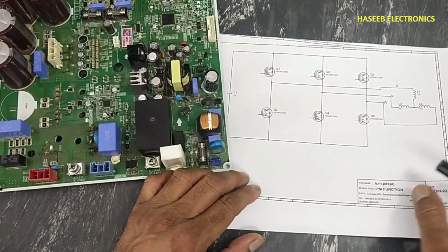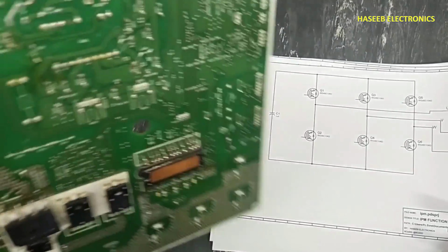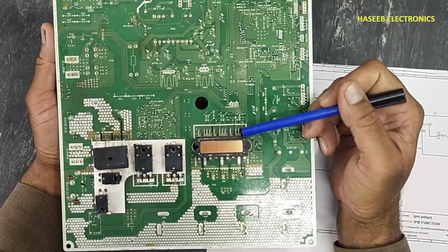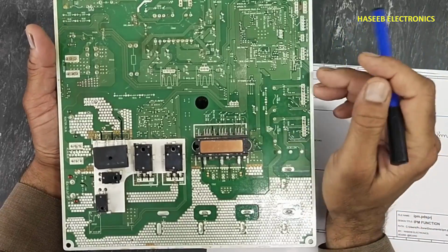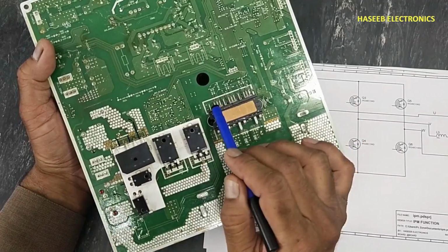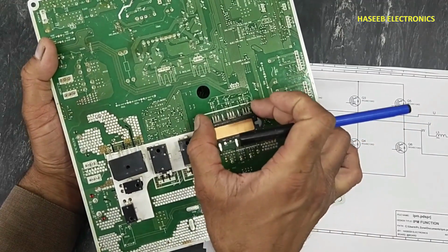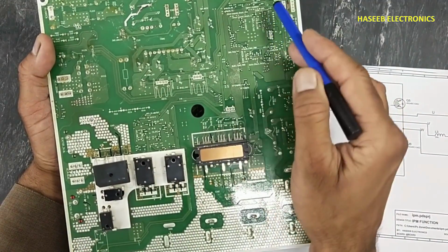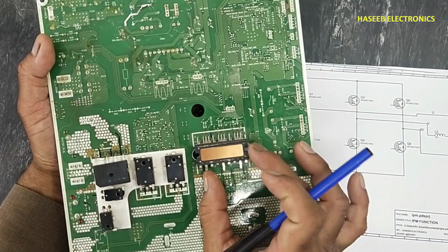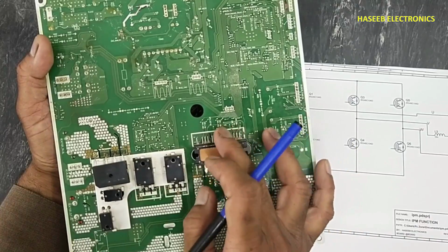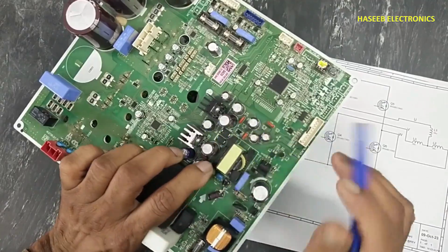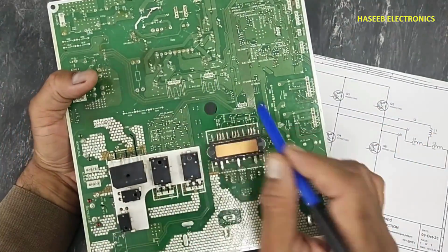How microprocessor will provide commands. In IPM section, it is intelligent power module. It contains drive section, that is low power drive, low signal drive. 6 drive signals will reach here. Then it needs power supply. Power supply 15 volts will come from this capacitor. 15 volt power supply,